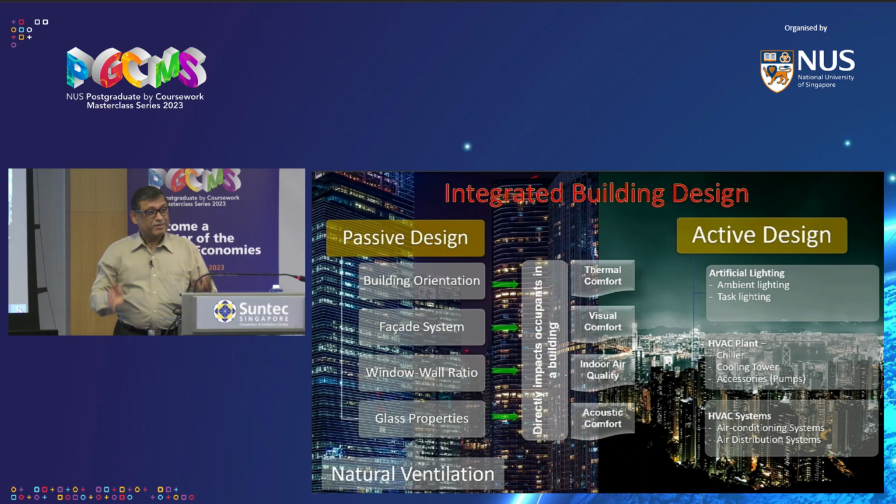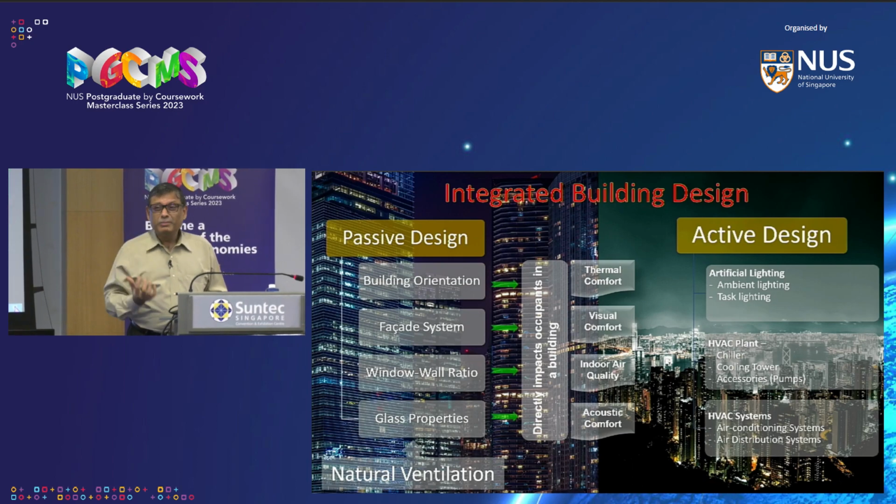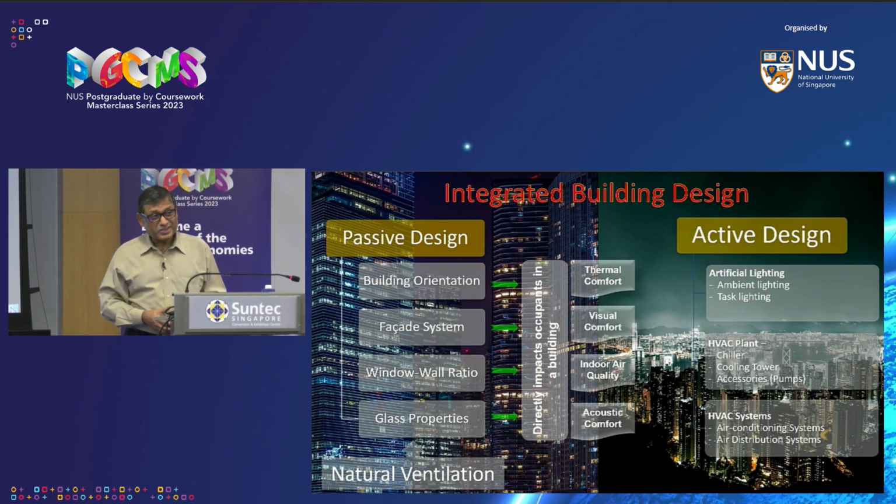If you put everything glass, a lot of heat goes into the building. We want to try and minimize the amount of heat, but you can't just put walls so that you don't have a view out. So these are all the architectural elements that we need to understand and incorporate into the building. So how much window, how much wall has a role to play? And it's a passive energy design optimization.